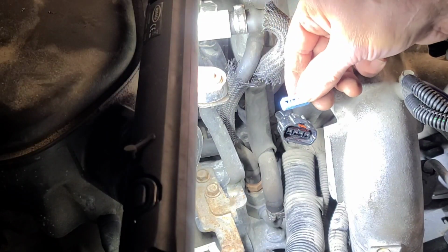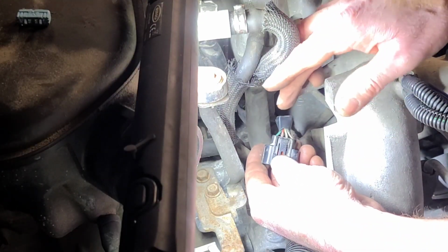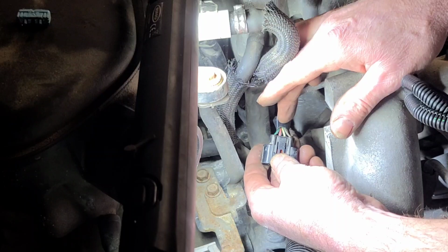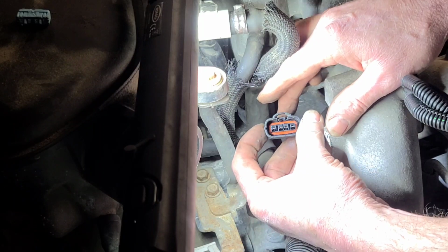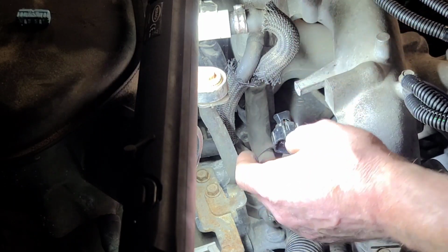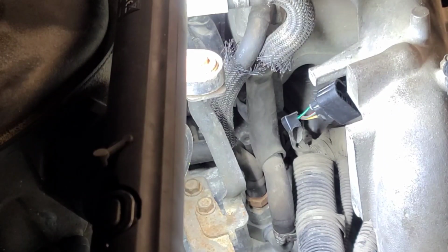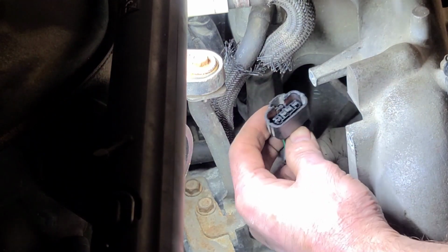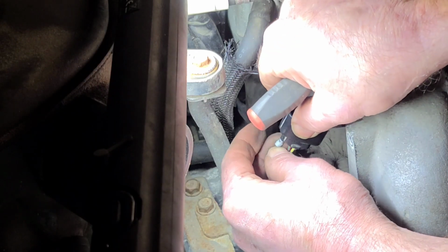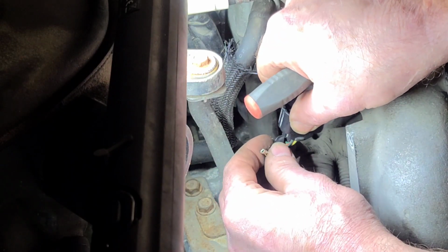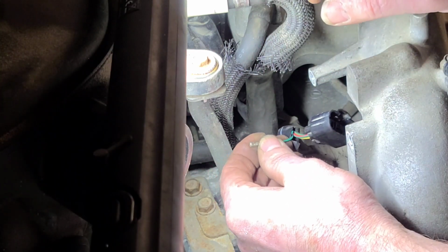So the blue plastic secondary lock just pops out of there, and the terminals are oriented green with a black tracer, red, white, that's either yellow or beige, and brown, looking at it from the top. So I'm going to de-pin all these terminals and reshape them. To release these terminals, you need a little tool to reach down here and pry this plastic apart and pull out on the wire at the same time. Those terminals are pretty tiny. I wonder if I can buy this pigtail.